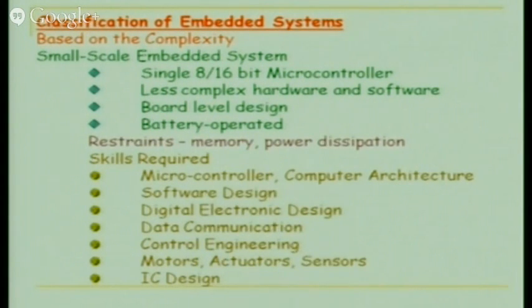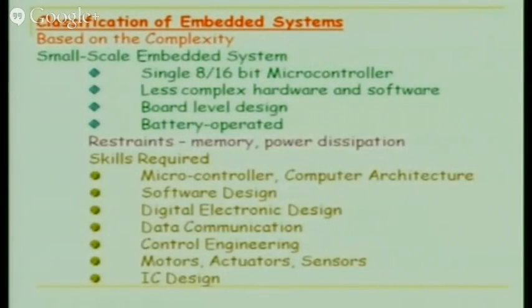And the skills required while you design a small scale embedded system, which probably applies to all of you since you are beginners: you'll have to get familiar with computer architecture, microcontroller, software designing. You should know detailed electronics, because sometimes you need to design some logic, 0 and 1, AND, NOR. These are required to design particular control signals, because you have chip select, output enable, this kind of scenario comes while you design in the real world.